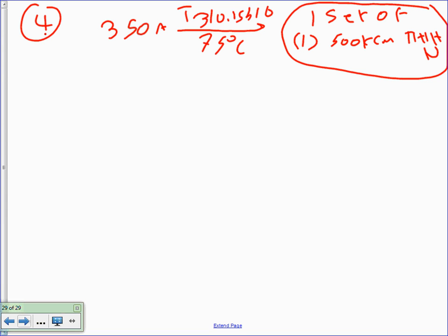A lot of engineers take the size of the phase and drop 2 to 3 steps below, you know. So 700, what's the next step? 600, I think. Right. Go one more step, 500. So 2 steps: from 700, one step gets you 600, one more step is 500. And you can even go a little bit further, what's after 500? 450? Yeah. But if you don't know, it's a good assumption. We're not matching the neutral, but going by the actual load. That's a good assumption.